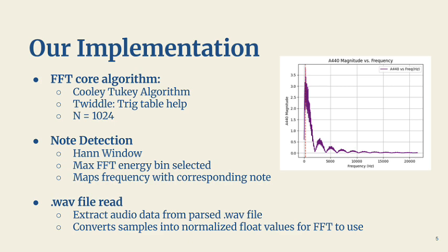The two additional functionalities were added as we wanted the program to be more application-like and have connections to real-world scenarios. First, for the FFT core algorithm, we used the standard Cooley-Tukey FFT, which we already introduced earlier, so I won't go into details in here. One thing to note is that for the twiddle table that we implemented, we pre-computed all the required values so that we don't have to do complicated math in the twiddle table during the program.